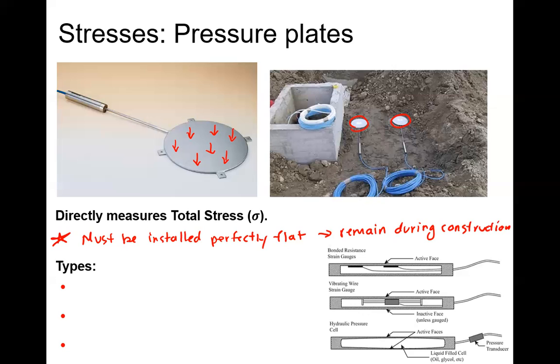So often when they're installing these, they don't just chuck them underneath and then start loading soil with the front loader over it. You need to dig a hole underneath it, take your level and make sure that it is perfectly flat and on a strong base, and then pour soil over it.